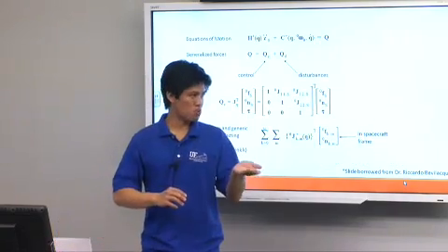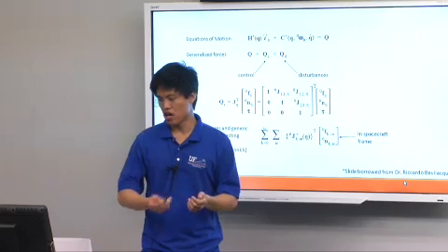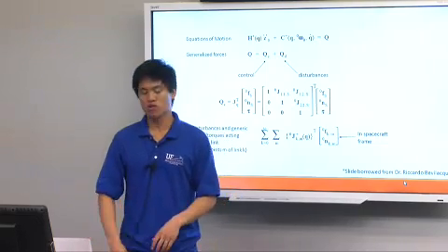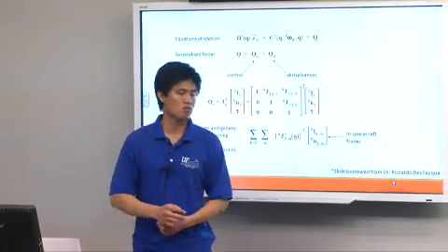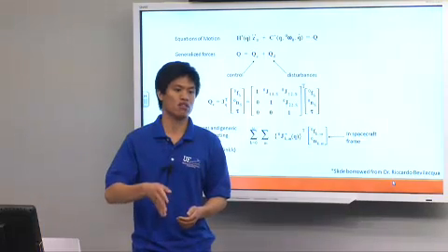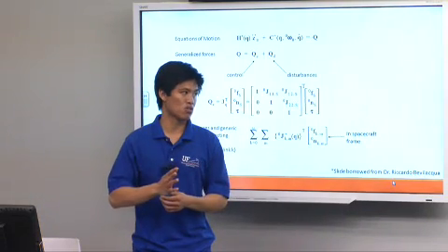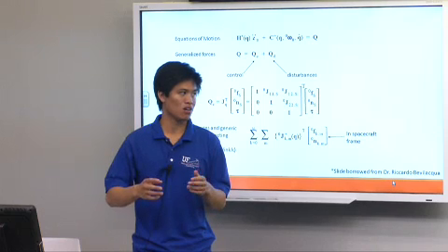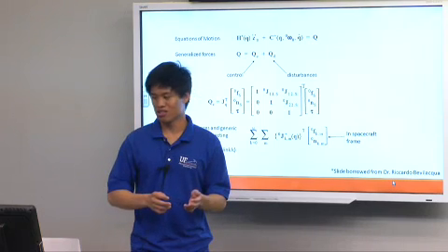But you pretty much go through that, and you get your equations of motion, and they're pretty much in the form of an inertia term times the accelerations of the independent generalized coordinates, plus something we call the centripetal Coriolis.